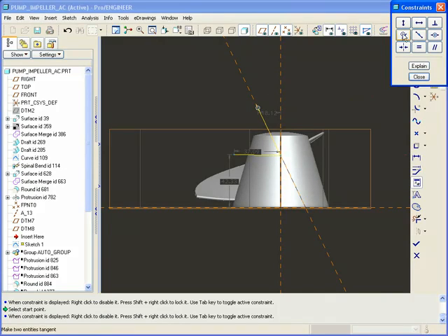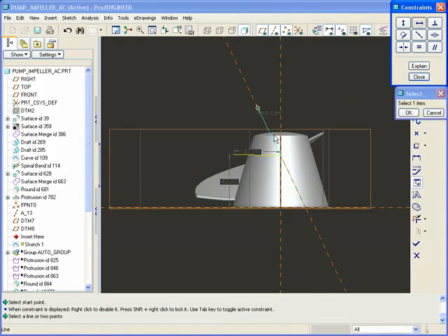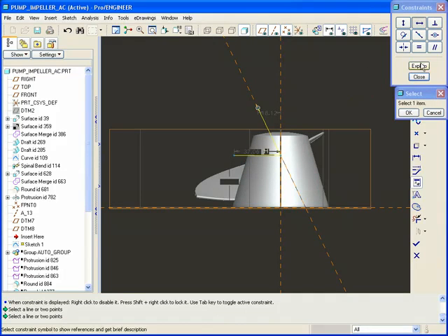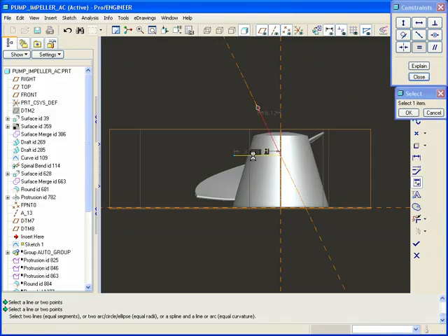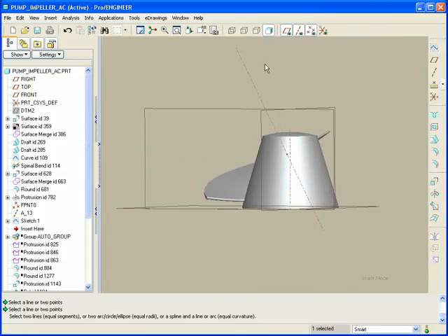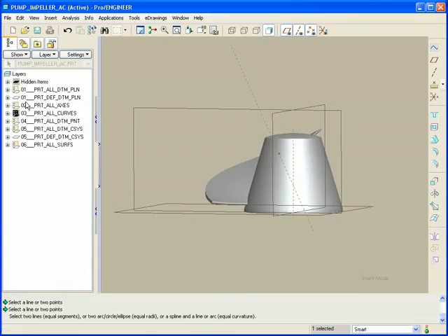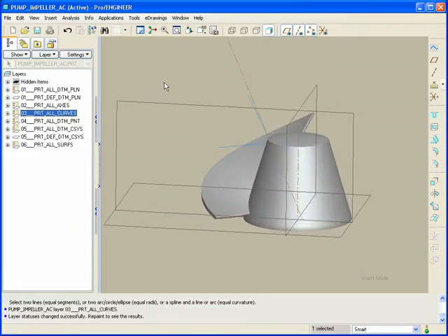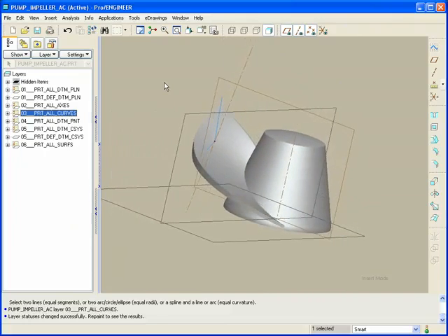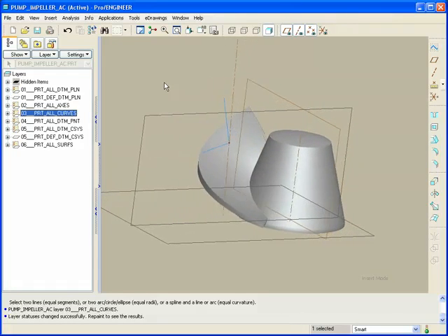Using some geometry references here, we'll specify this is to be exactly horizontal, and we'll just make these two equal to each other, just for grins. Now, we have a curve, and they're currently turned off, so let's unhide them. So there is the slope angle that we're interested in.